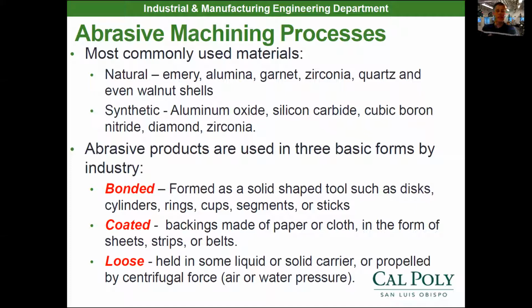Or maybe even just a stick. You could have an abrasive bonded to a stick. I have basically an abrasive stone that's just a stick that I wipe on the CNC table, or use to stone the CNC table to make sure it's nice and flat before I put my vises down there. So that's bonded ones.